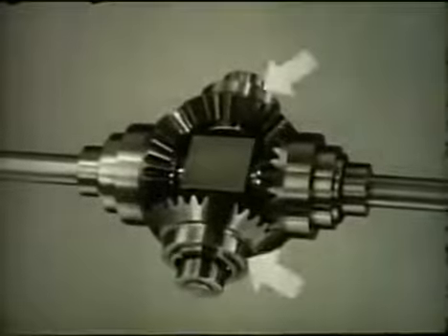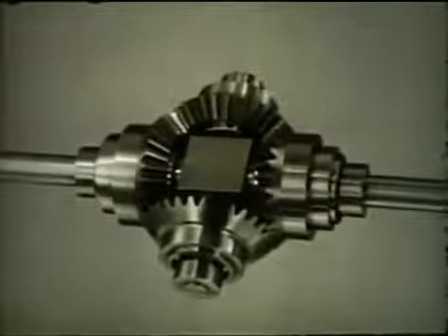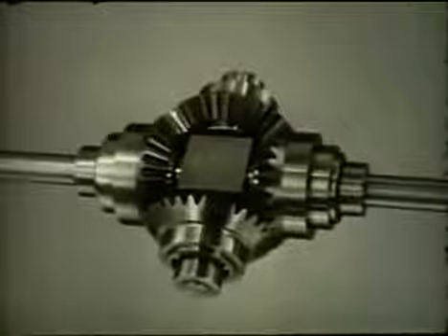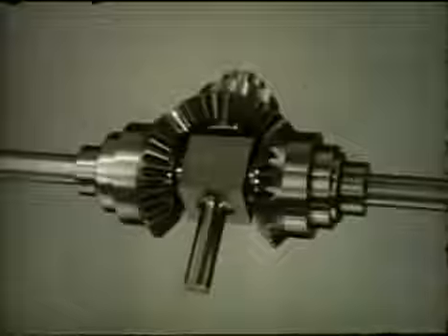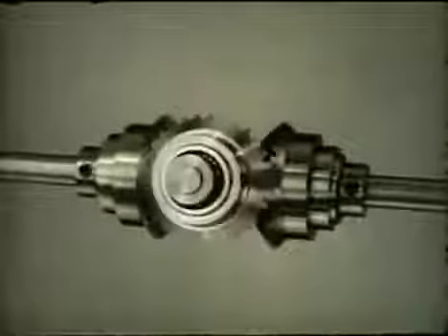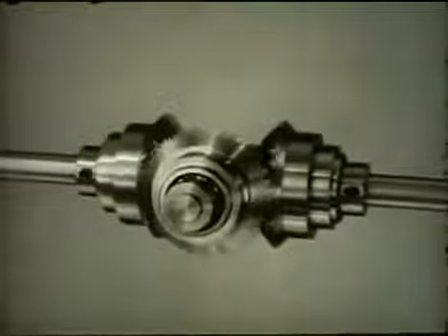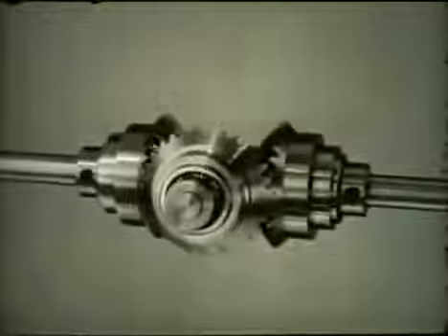Although there are two spider gears, only one is needed for the mathematical problem. The other is there to balance the mechanism. So we can remove one spider gear, and we now have the basic elements of a differential. To study its operation, it is necessary to count and compare revolutions of the end gears and the spider shaft. That isn't easy to do.